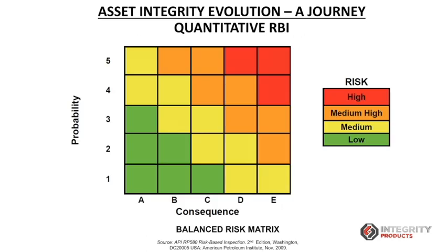Here is the real benefit of the RBI process, I would say quantitative RBI. It's a detailed RBI process, so we come to know which system, which equipment, which piping or loop is vulnerable to CUI and to what extent. We can see what is called a 5x5 matrix.